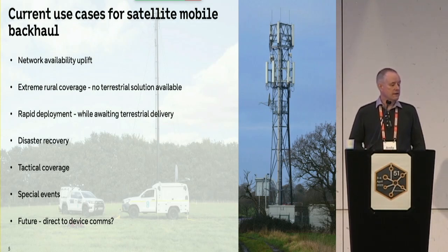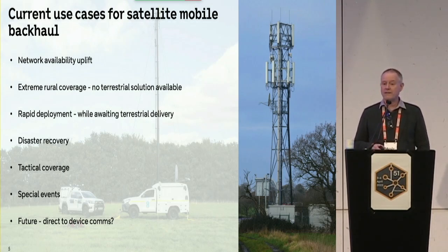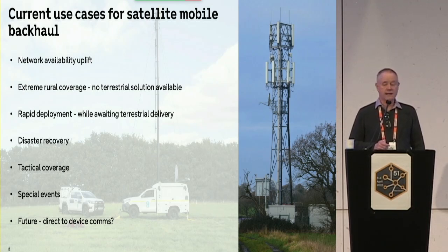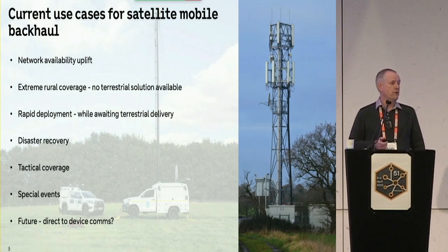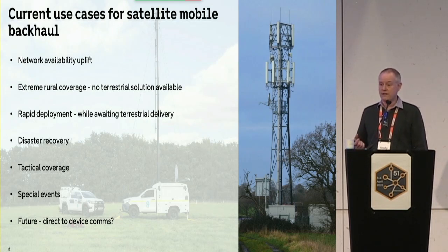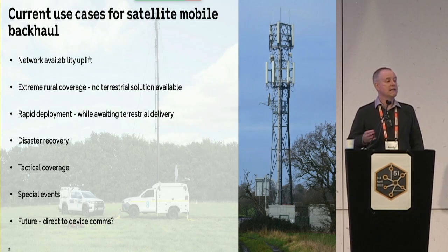Other use cases include rapid deployment. So quite often, if we want to build a cell site and connect it to the network, we could be waiting for wayleaves to deliver fibre optic connectivity, or indeed a radio channel assignment from Ofcom for a point-to-point microwave radio. We can deliver satellite capability, we can integrate the site, we can start to offer service, and then deliver the terrestrial transmission once it's available, and either leave the satellite if it's needed for resilience, or indeed remove it